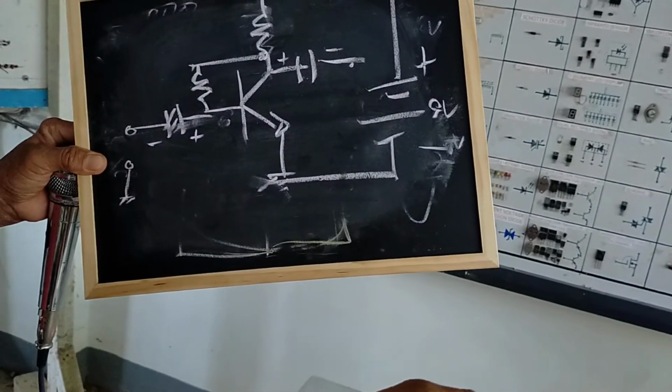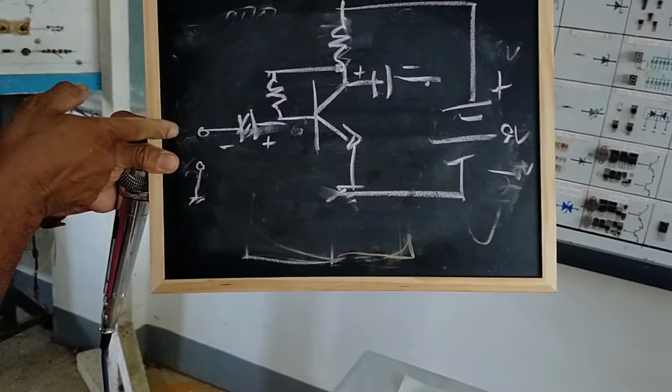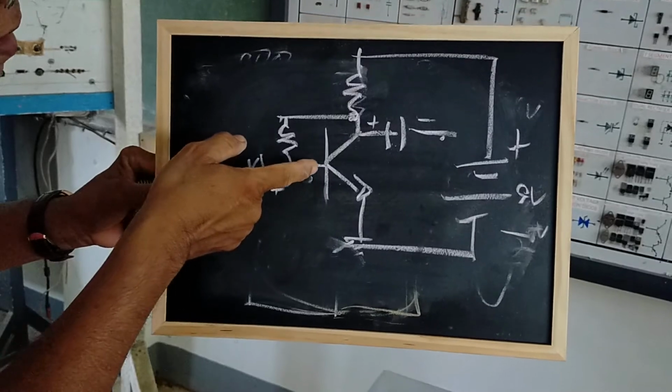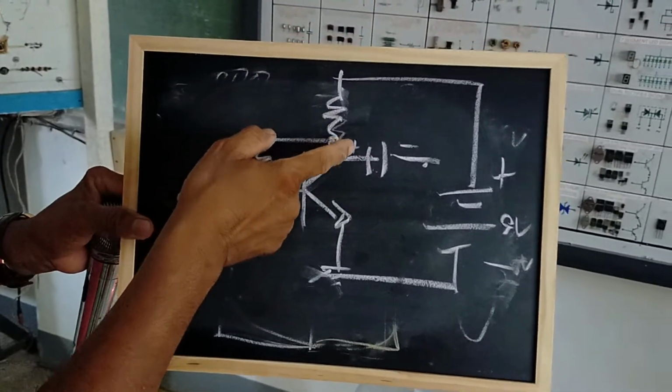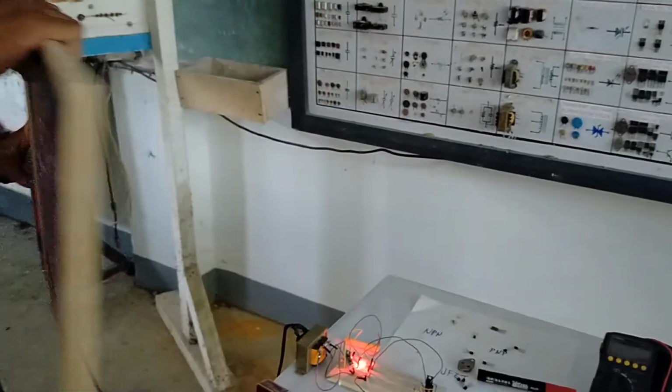The signal, 0.566 volts or 566 millivolts, is actually fed here. Then the output is taken at the collector, which is connected to the oscilloscope. You see that the signal amplitude is enlarged, or amplified.